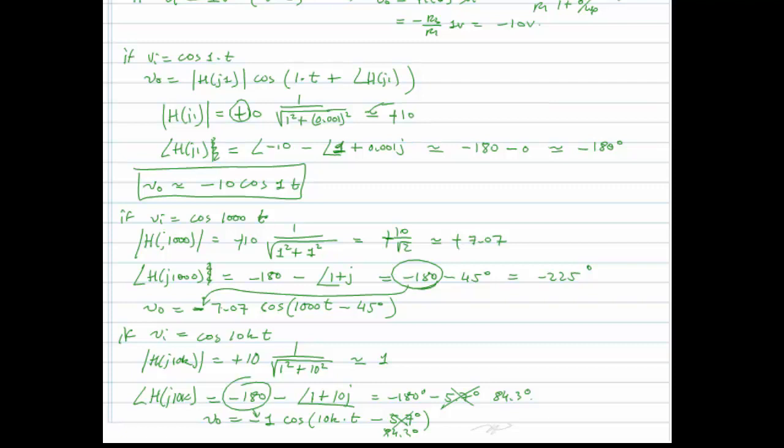So what's the use of this? This would be a useful amplifier if we have some sensor, could be a microphone, could be a temperature sensor, where we really want to capture the, let's say it's a temperature sensor. I really want to capture the DC, or the steady, the DC temperature of the room. But I know there's noise in that temperature, or maybe that temperature fluctuates because doors open, doors close, and I don't want to respond to that.